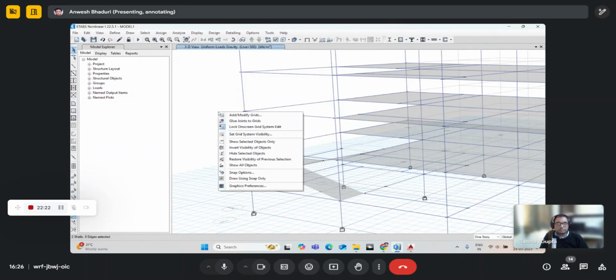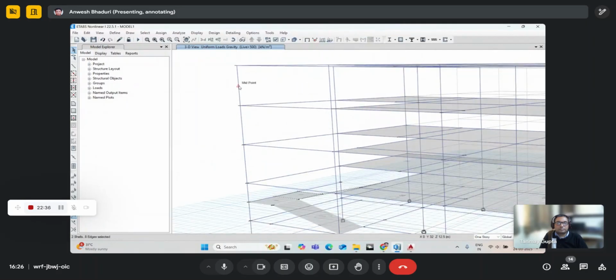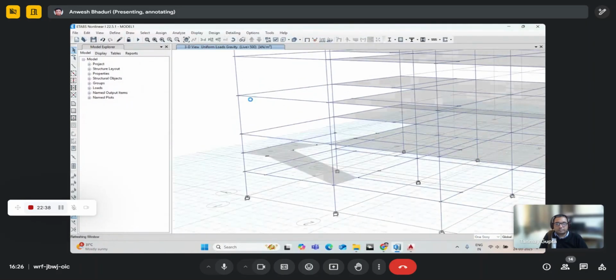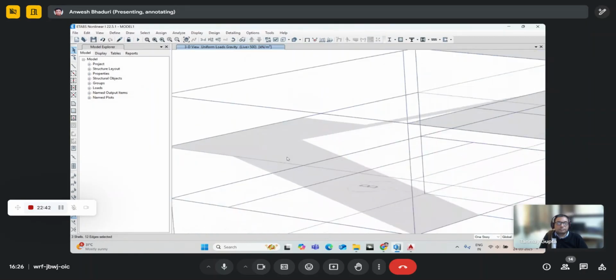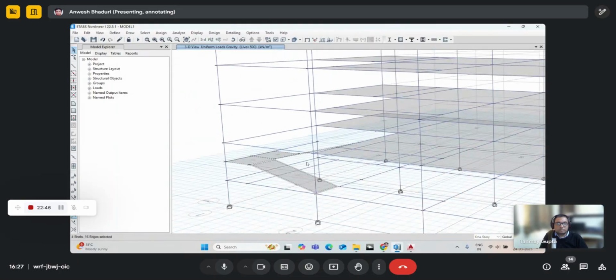I have turned on the snap to midpoint option, so we can directly go to the midpoint and check what is the value of z at that location from the right hand bottom corner, and insert reference planes at each and every midpoint for modeling the staircases. Otherwise, if all the floor heights are constant, we can select the staircase from here.